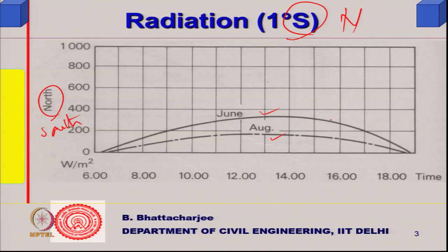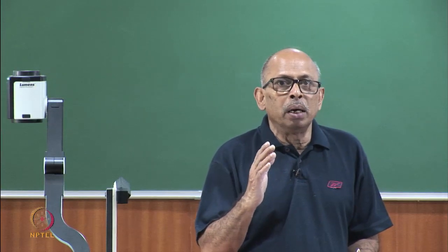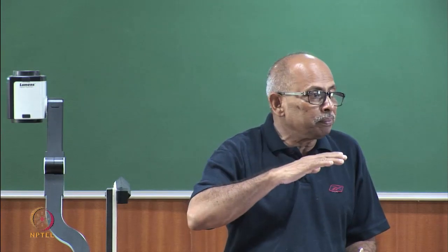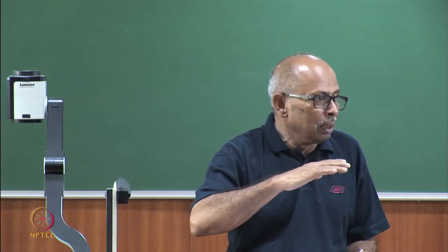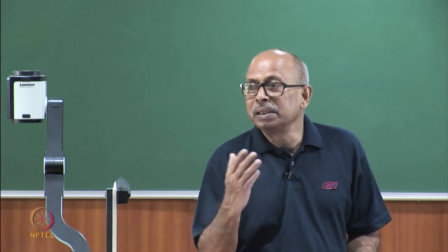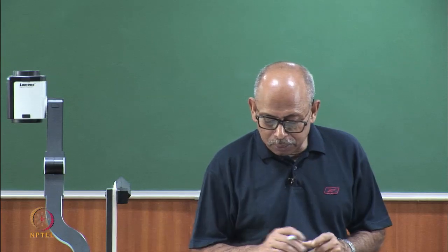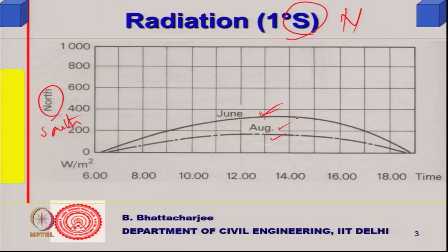So, for example, in south surfaces, in winter months the sun's altitude is less, so the south surface gets a lot of radiation, but in summer months it will get less radiation, right. So, winter months it keeps on getting. Here, for the southern hemisphere north surface, these are actually winter months, sorry, these are winter months; the corresponding ones in our case should be reverse ordered. So, this gives us some idea.